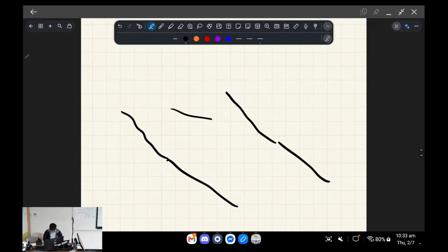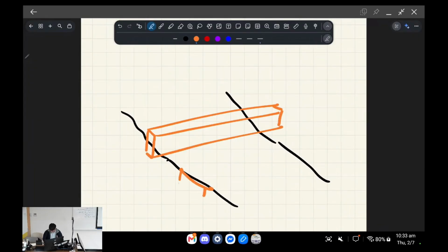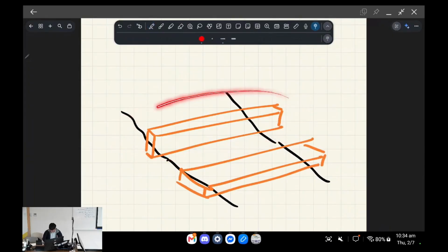Okay, and so there's like water there. Let's say you've got a piece of wood that can be orientated like this or like this, okay? So this way you've orientated the wood flat, and this one it's on its edge, okay? So if I was to walk across this river, which bit of wood would sag more? Which bit of wood would be less stiff? Yeah, the one that's orientated flat, we can intuitively tell is going to sag more, right?